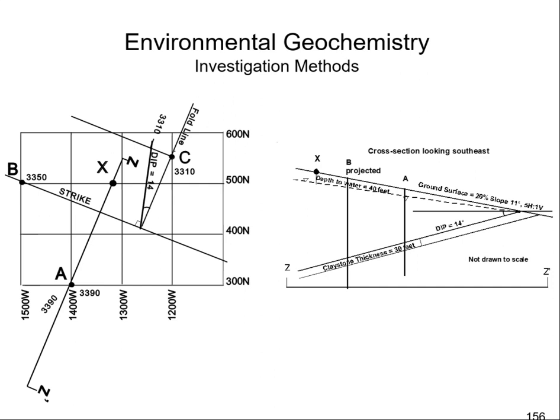Then it has all this, the tank location and the elevations to a bed that's in the subsurface. Now this series of questions about this could have started out with, what's the strike and dip of this bed? Because you have the 3 different elevations given to you at the locations given in the coordinate system.